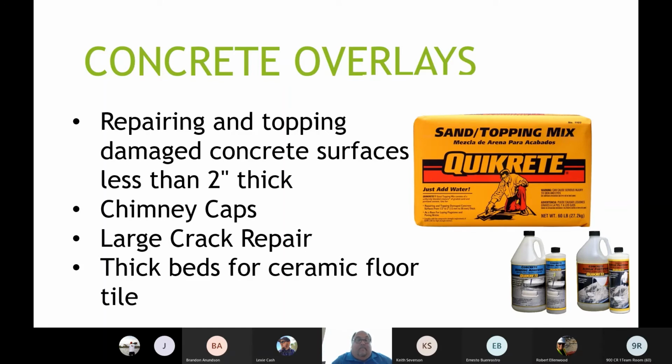Man, the slab might not even be 5,000 PSI. You're actually stronger than the slab. It's sometimes easier just to keep it simple. If you want to get tricky, I've got products for you that'll work for that. We'll definitely make it a super material that's a little more tricky to use, but still with this, I highly recommend getting the spec data sheet in the customer's hands, or at least letting them know where they can find it on quikrete.com, so that way they do the proper curing and stuff like that.